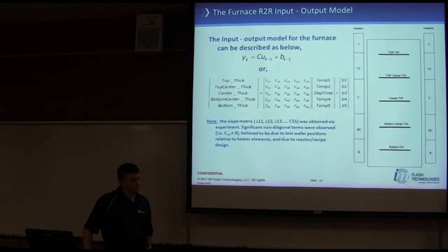So I would say a lot of we're controlling things in the angstrom range, right? If we're running 15 etch chambers for one process step, no two chambers of those 15 are exactly the same. So we heavily rely on feedback to keep our tools matched from a process point of view. And we rely on feed-forward to try and minimize incoming variation as possible.